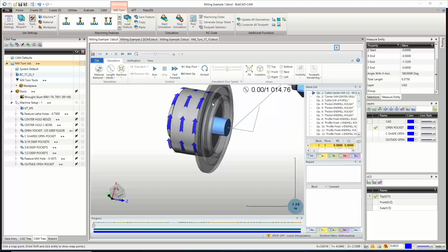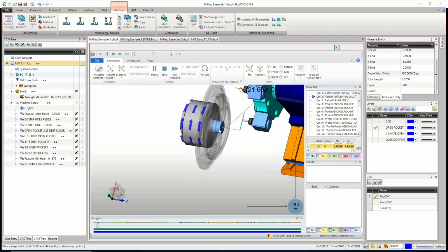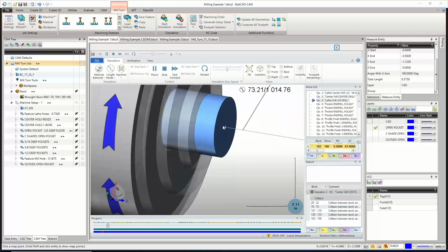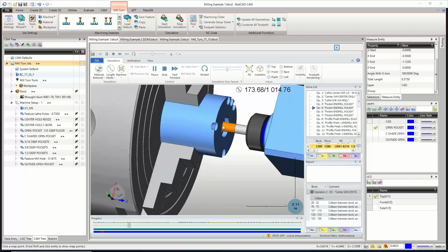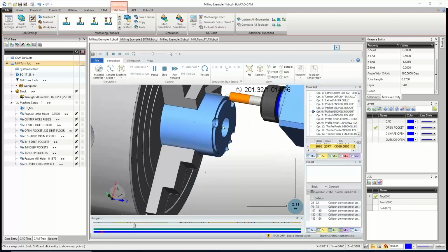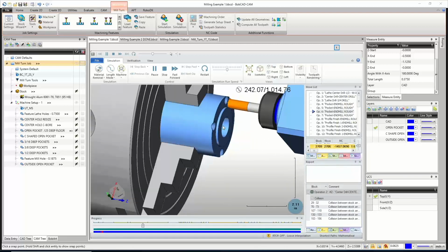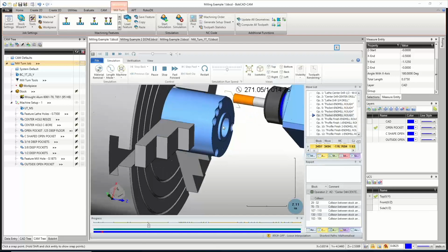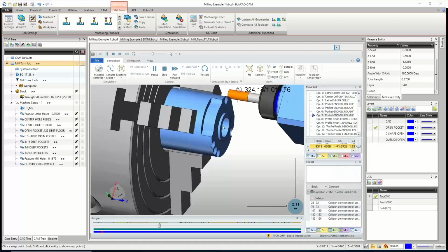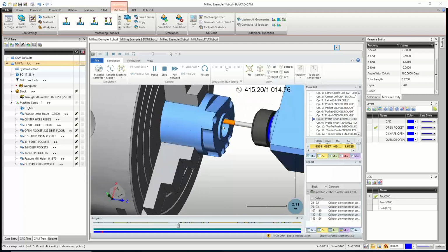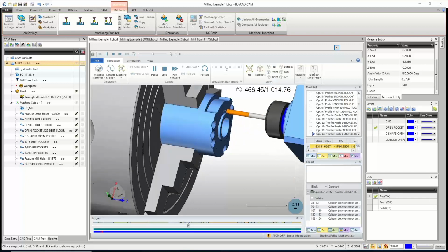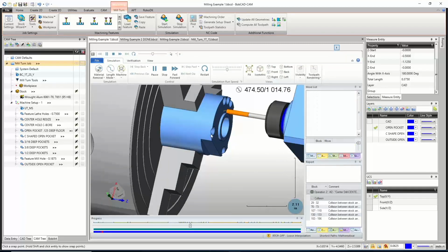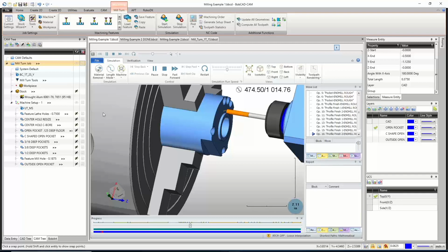A lot of times drilling happens very quickly. So I'm just going to go ahead and say run. And we have some ordering issues going on here. So we'll have to fix that because we did all of our center drills. We're probably grouped right now by individual tool. So it's trying to keep the same tool running as long as possible, which a lot of times is used if you didn't have a tool changer, which is not really the case when we've got a turret here. So let's fix that real quick before we get too deep into the simulation, because we got a bunch of gouges happening. And so machining order is super important.